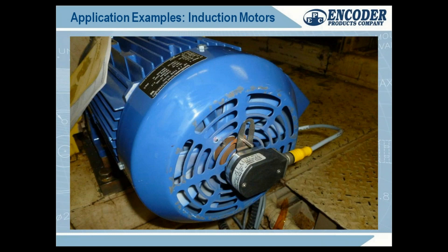So a lot of applications now are asking for induction motors that have feedback on them, or induction motors in the field where you need to install feedback. We sell a variety of encoders that you can adapt to motors with subshafts that will mount directly to fan shrouds, or have NEMA mounts to go to the back or the front of induction motors. That is becoming one of the most common applications for encoders, even more than it used to be. And encoders have been on induction motors for a long time.